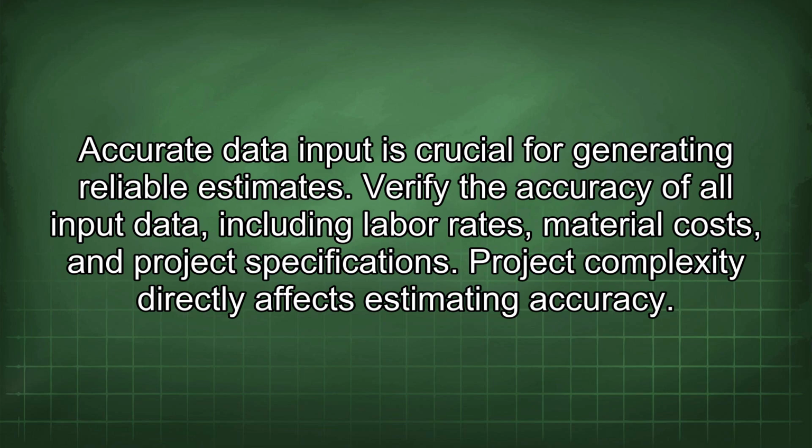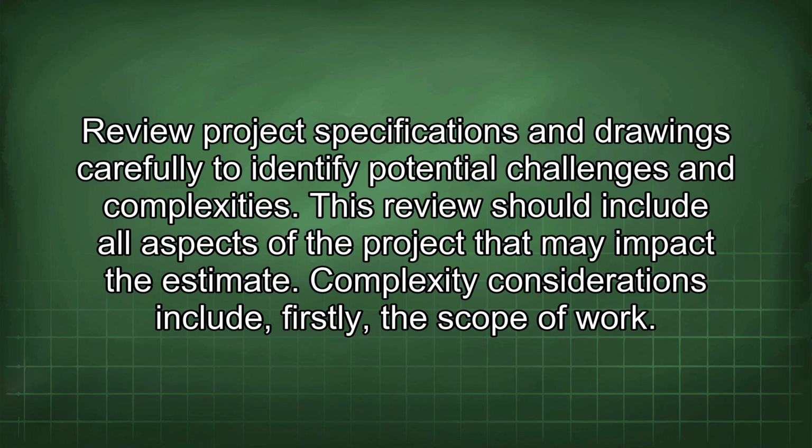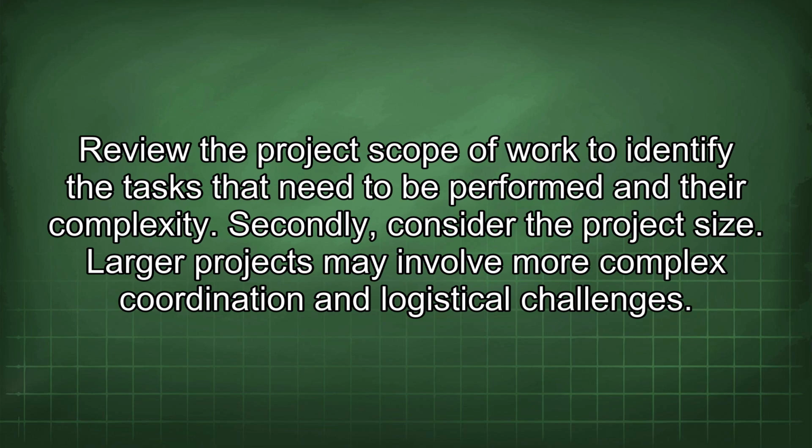Project complexity directly affects estimating accuracy. Review project specifications and drawings carefully to identify potential challenges and complexities. This review should include all aspects of the project that may impact the estimate. Complexity considerations include, firstly, the scope of work. Review the project scope of work to identify the tasks that need to be performed and their complexity.